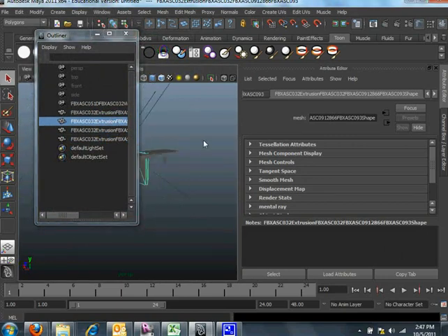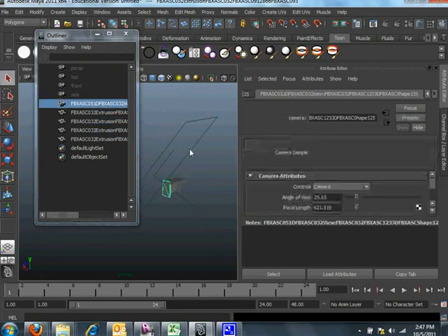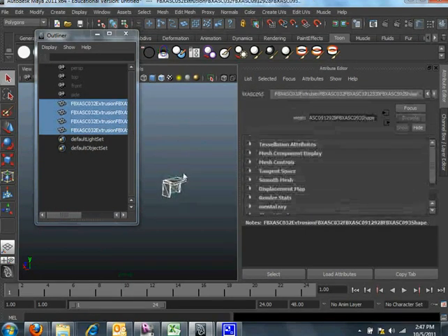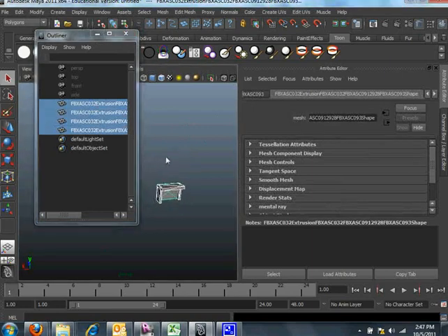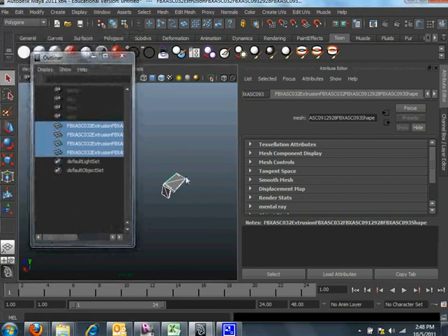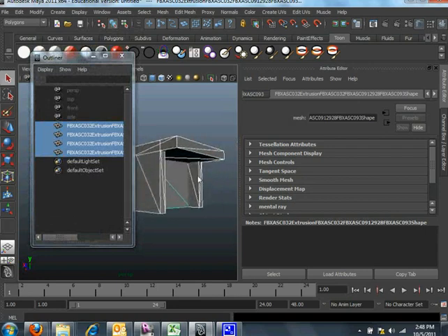Another thing I want to mention is the green line is actually the camera. I don't need this. Delete that. Another thing I want to mention is Maya is Y up, so the y-axis is facing up. Revit is Z up. So sometimes when you transfer a file in, you may see the geometry rotate 90 degrees, just because one is Y up, another is Z up. It's not really a big deal because when we have this geometry, we can easily rotate 90 degrees.